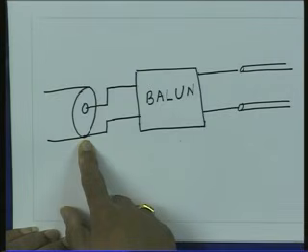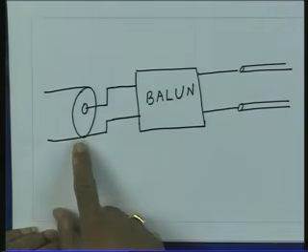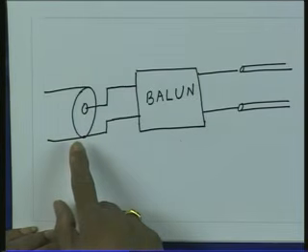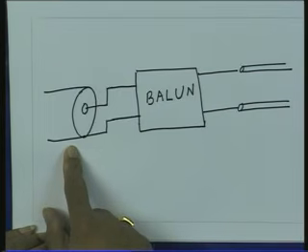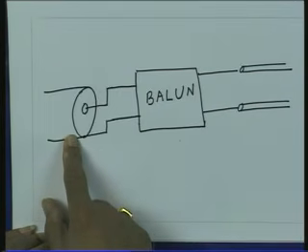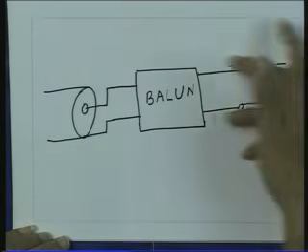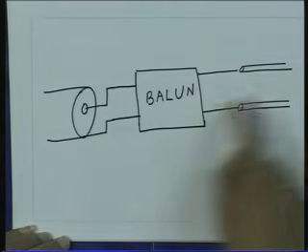Then there is a small black box which is kept just at the input of the TV, because the connector which you have on the TV is a coaxial connector. So, that connector is an unbalanced connector. Also the impedance which you see here is 50 ohms, but the flat ribbon cable, that impedance is much different compared to the 50 ohms.